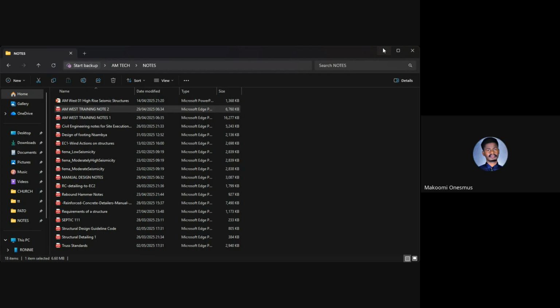Now, the spacing will come later, when you are trying to be economical. At first, you leave out this thing of being economical. First, consider where two grids meet, there should be a column. Where two lines meet, there should be a column. Those are the two key things you should consider. And then after that, the next thing you should consider is the spacing.